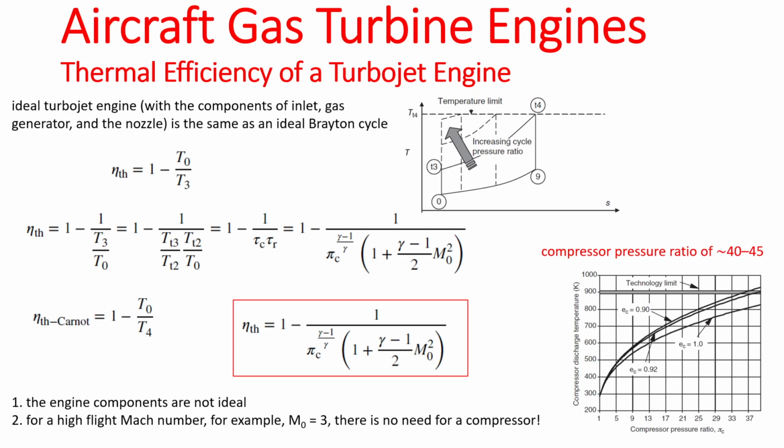It just seems like you wouldn't have as much power because the whole point of the combustion stage is to increase the heat, which would increase the speed of the gases. And if they're going in at relatively the same temperature they're going out, I feel like it's going to drastically decrease power. Okay, so what you're saying is that you're putting in less power, right? Because the temperature change in the combustor is going to be smaller.